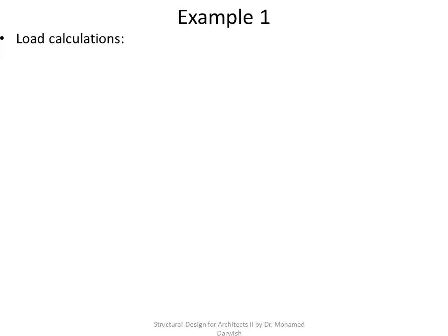By the way, if you are in a hurry in an exam or something, you don't actually need to calculate the L effective and that stuff. You could just take the L effective as 3 meters, because as you could see, the difference between 3 and 2.9 is not that major.